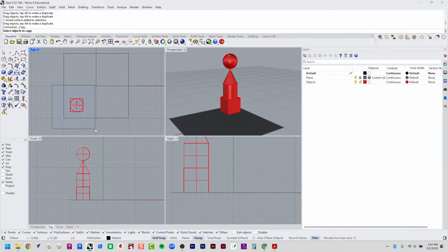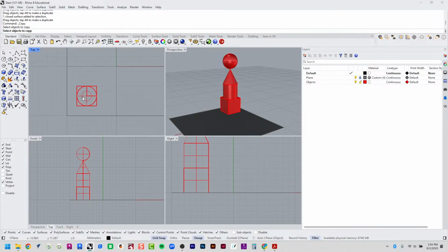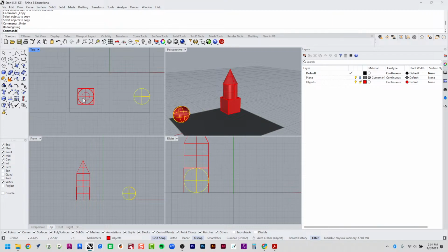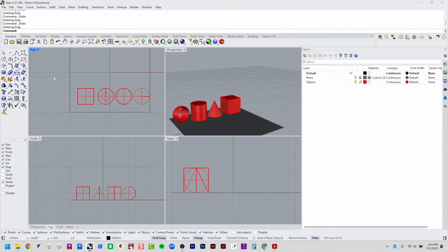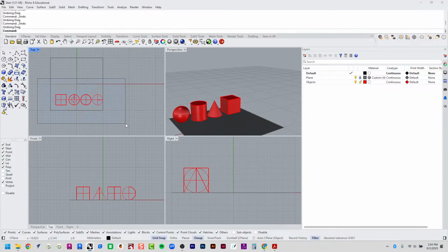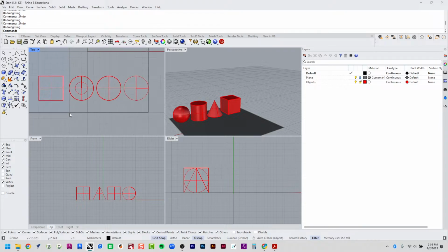Here's a real important lesson that I'll introduce to you all early on. If I am making a selection window, which looks something like that, just me clicking and dragging my cursor to make a window just like this, when I make a selection window that goes from left to right versus from right to left, those are 2 different things. Let me explain.